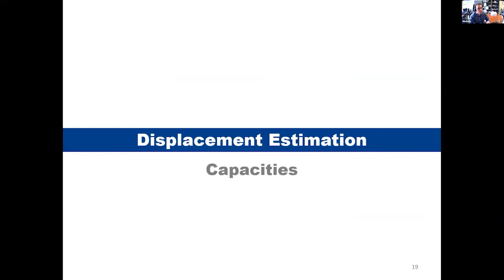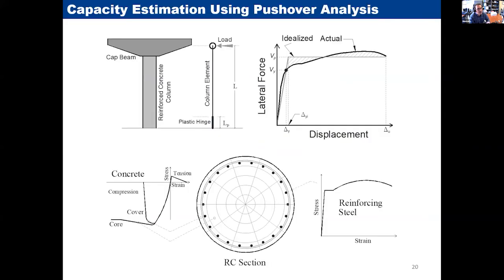So I know how much displacement demand I will get by using the picture of the column damage. How about the capacity? With the most advanced tool, like what Dr. Pendeltis was discussing in the previous presentation, we can use OpenSees, perform a pushover analysis, and get a force displacement relationship. This is the yield point.